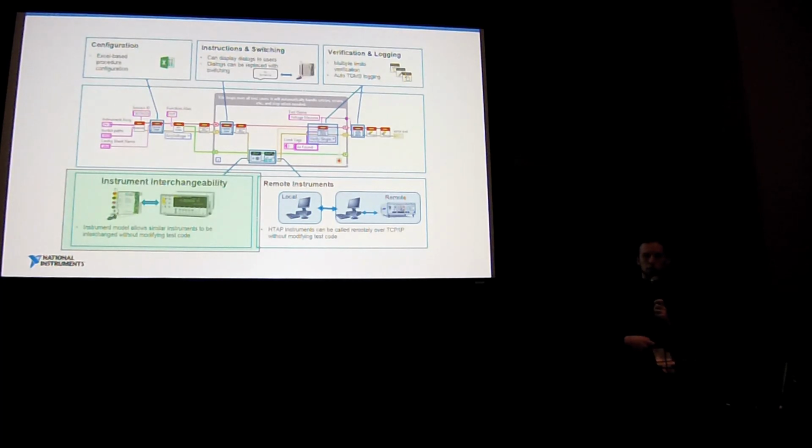That instrument is the driver code that implements the interactions with the hardware. And you can see that alias aspect here. When you initialize these functions, you give it an alias or a tag, and now you can pull it out like, this is my device under test, and that's how I'm going to address it. Or this is the source or the sink for my test, or whatever you want to call it. That's how you make that mapping.